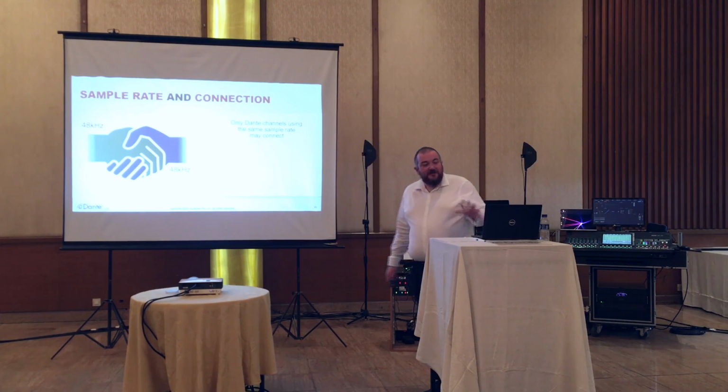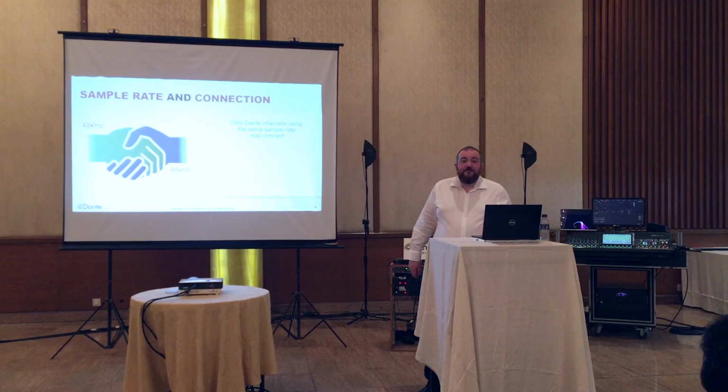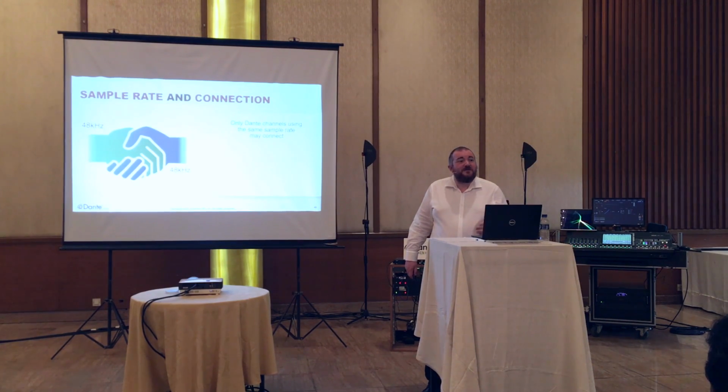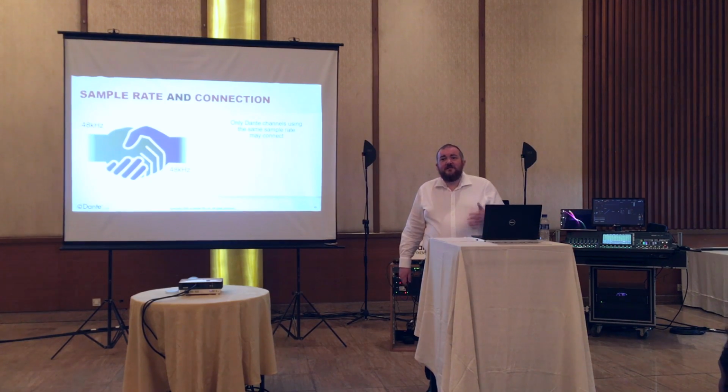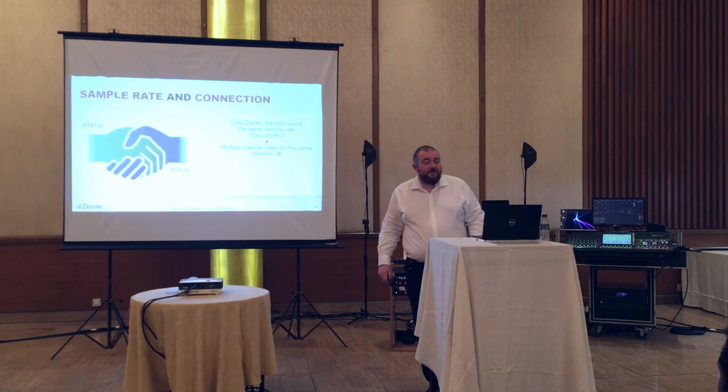So, sample rates and connections. Only channels with the same media profile will connect with each other on Dante Controller. So we can have multiple sample rates running within the same network at the same time, and they'll all be synchronous. It's just that we don't do sample rate conversion in a Dante network. So I can't connect a 48 kilohertz channel to a 96 kilohertz channel, which is a good thing because we're now doing video, and we can put video into the same network as well. And you really don't want to be connecting video to an audio device. It doesn't sound very good. So Dante will prevent you connecting video channels up to audio channels and prevent you connecting wrong audio channels to other audio channels. So that's very useful.